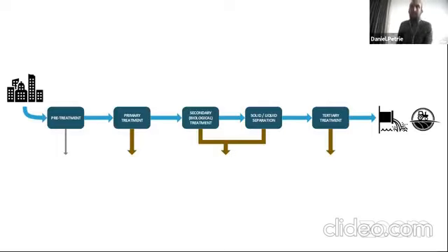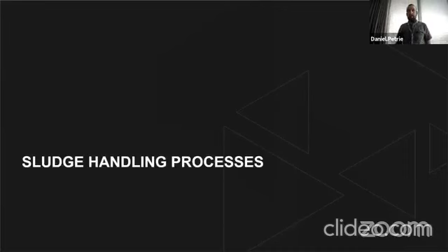And while it's helpful to think that this is where the solids are going, those solid liquid separation steps are not very sophisticated. So we're really transporting a hell of a lot of water with those solids. They're still very much in a liquid slurry, at least 95% still water. Now we've got to figure out what to do with this very liquidy stream where you're trying to isolate the solids.